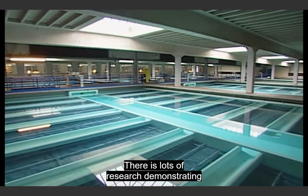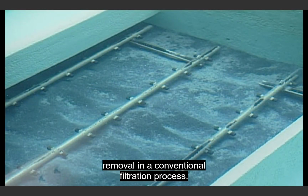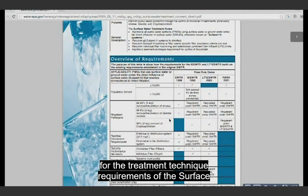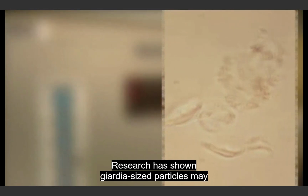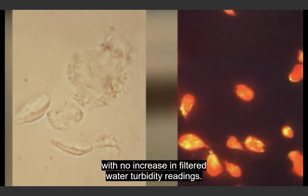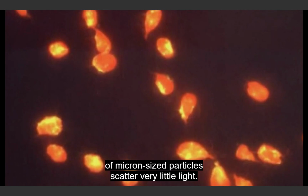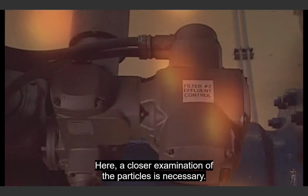There is lots of research demonstrating that turbidity removal is a good surrogate for Giardia removal in a conventional filtration process. In fact, that is the underlying basis for the treatment technique requirements of the Surface Water Treatment Rule. Research has shown Giardia-sized particles may pass through the treatment process with no increase in filtered water turbidity readings. That's because small concentrations of micron-sized particles scatter very little light. Here, a closer examination of the particles is necessary.